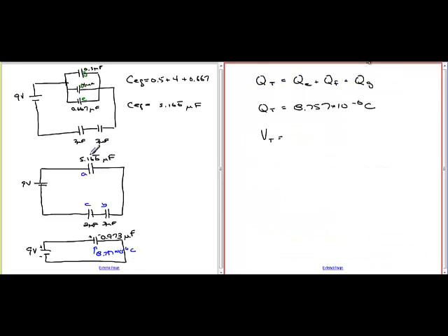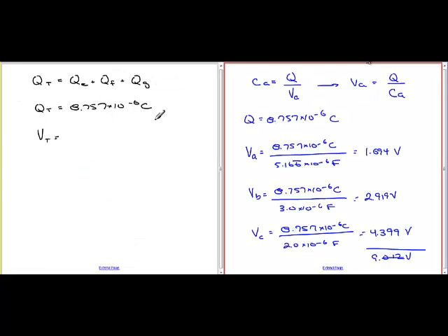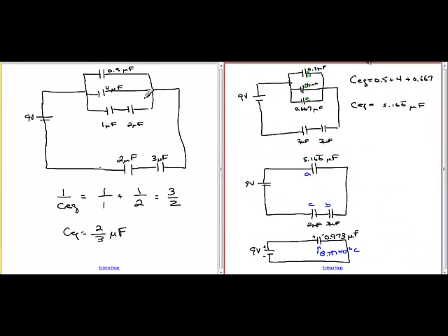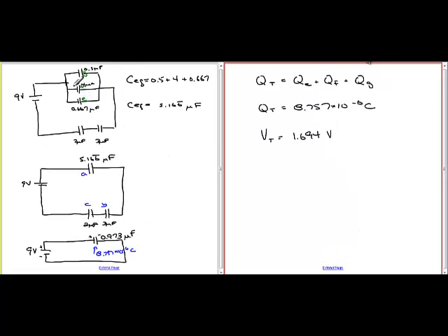So that's going to go back with the same voltage. So we can say that the voltage drop across each one of those individual capacitors is the same. So when you go from here to here, this voltage drop is the same as the voltage drop across the whole thing. So that is the key.